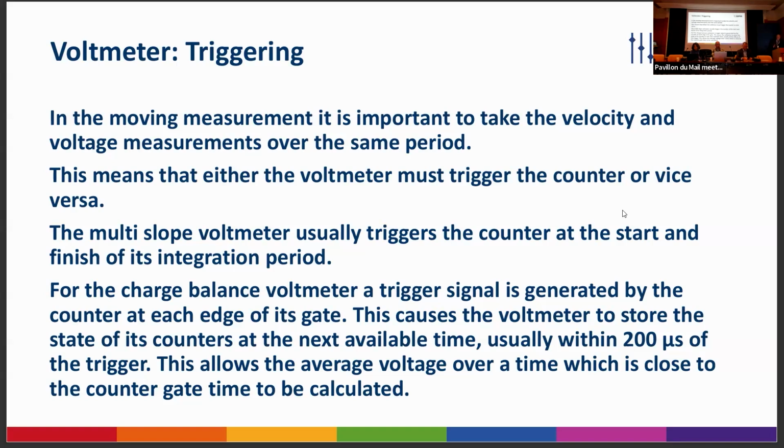So you've got some jitter on that, but as long as the energy in the voltage signal is negligible at that sort of frequency, you don't really care. Having an approximate trigger is perfectly good.